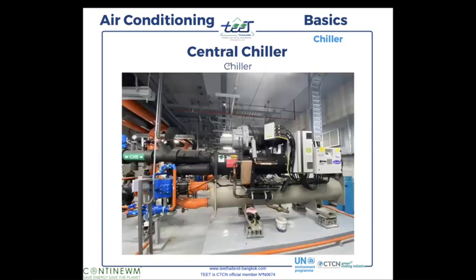Okay. And this is from the other side where you see very clearly. So this is the condenser. We see the other side of the compressor here. We see also that here, the refrigerant fluid goes into the condenser to get cooled. You remember, same as in the split type. And then after, somewhere here, we see going into the chiller to cool the water for the chilled water supply that goes into the FCU, AHU, and so on. So it looks complex, but actually, it's not so much.